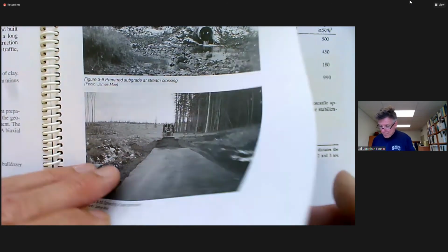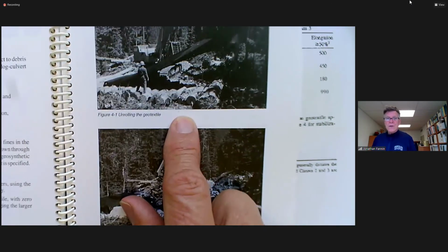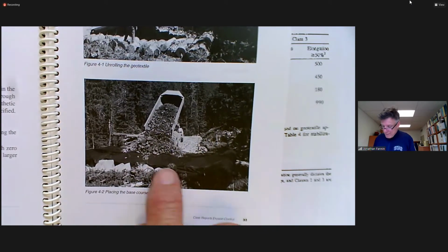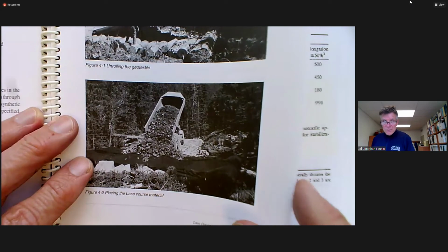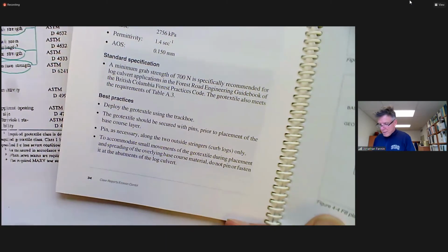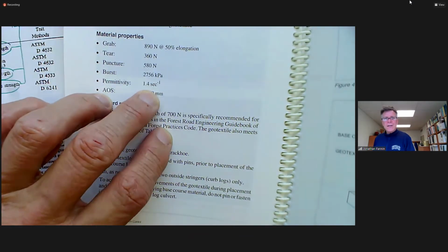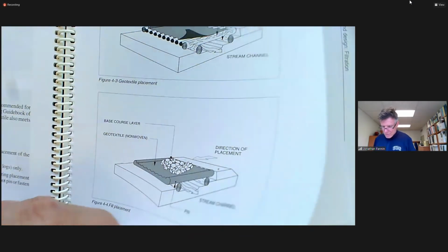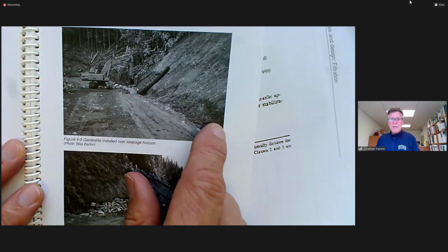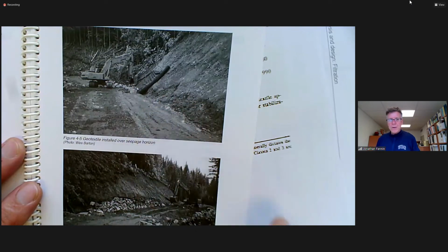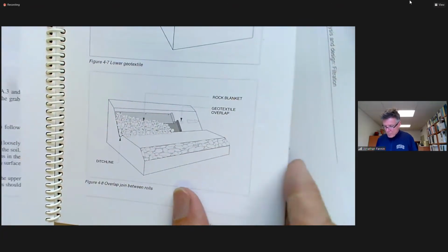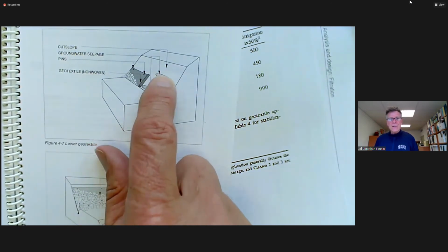And this is a geogrid. And log culverts, where you're stretching the geotextile over the log culvert and then end dumping, pretty aggressive. And we're not talking about tight engineering supervision. This is resource access roads. We looked at the grab, puncture and tear strength and the permittivity, and we looked at how it was done, and we checked it with the AASHTO specification. This is a little bit like the situation with Glynis Horrell, who was concerned to make sure you've got good cross-plane permeability. And applications with cut slope stabilization, and again, what was the grab strength? You've got to be careful of these seeps and so on.